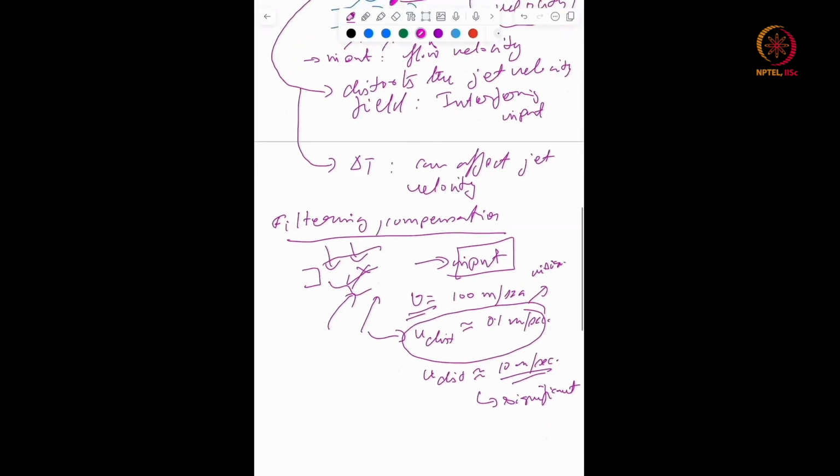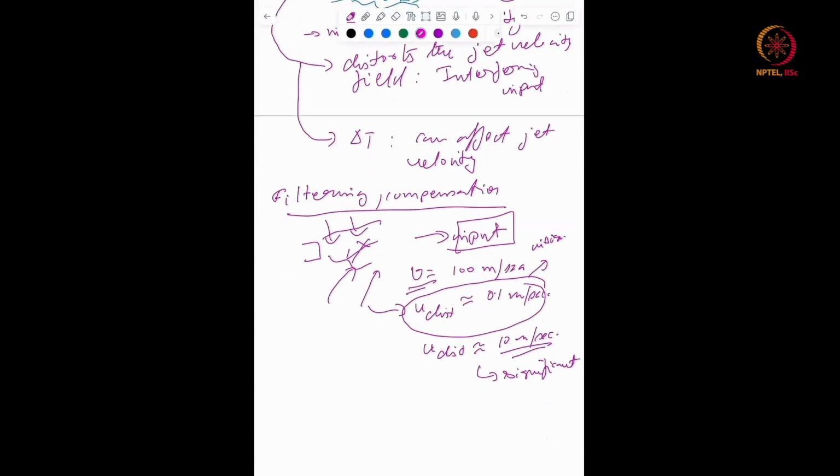Okay? So you need to redesign a component that is sensitive to the undesirable inputs in a way that it is insensitive to them. For example, you can use materials with near zero thermal expansion coefficient, which may eliminate the temperature sensitivity of a mechanical flow meter or a hot wire anemometer that has been calibrated to measure the flow in terms of displacement of some component.